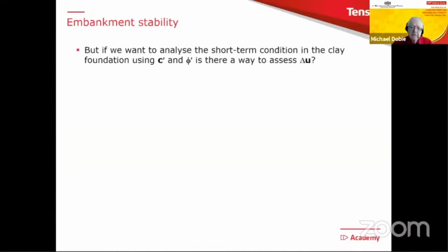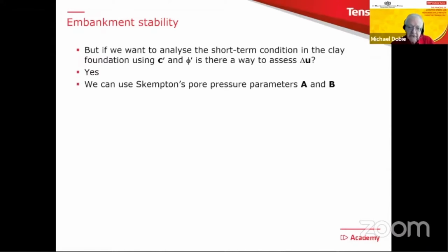But you might say, well, I'd like to try and analyze the short-term condition in the clay foundation using C' and Phi'. So is there a way to assess the increase in pore pressure? And the answer is yes. We can do this using what are called Skempton's pore pressure parameters A and B. And I would just like to mention them because they're going to come up again at a number of places in the remaining part of this webinar.